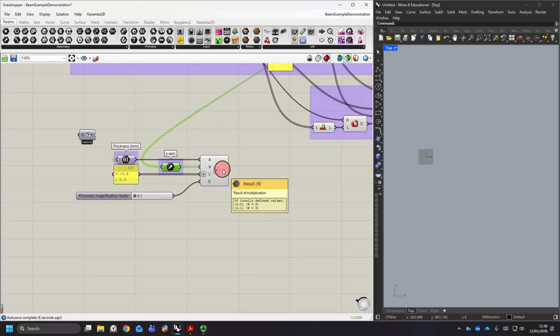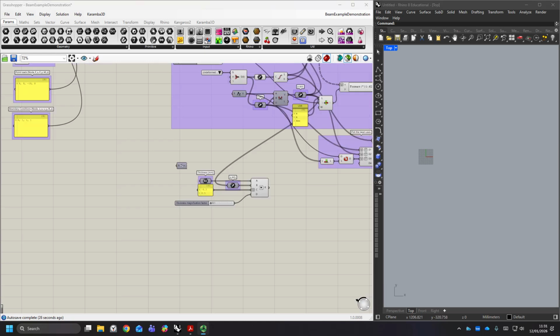So what this will do is it produces two sets of 8 points. So we had 8 elements in this case, and then those are the ones that we're going to be able to use to actually plot or generate the mesh for the contour plot. Okay, so what this is doing is it's generating the vectors we need, but obviously we do still need the points, and I'm going to allow the contour plot to be plotted either on the undeformed or the deformed shape.